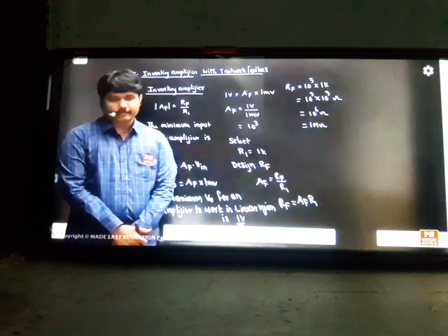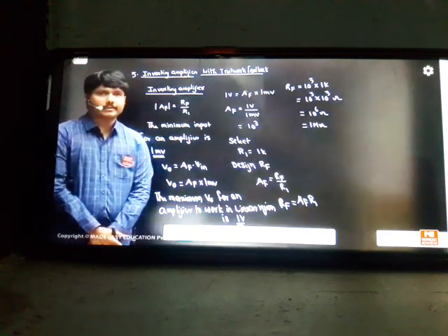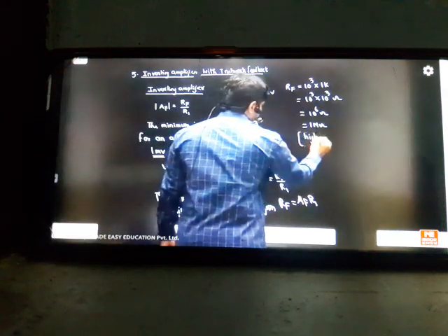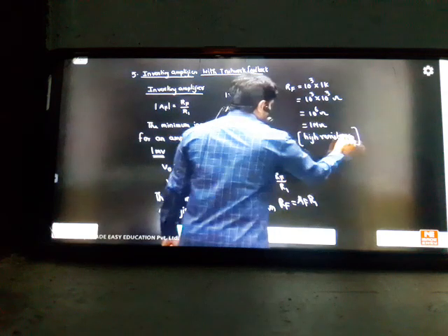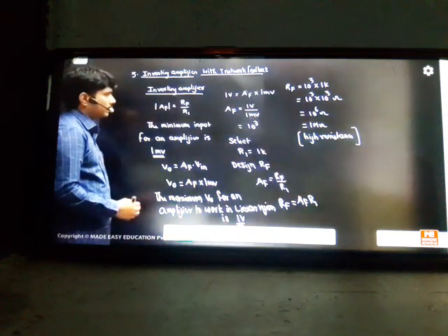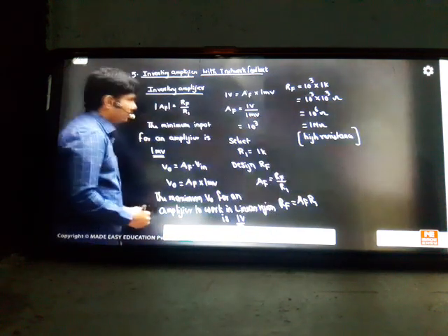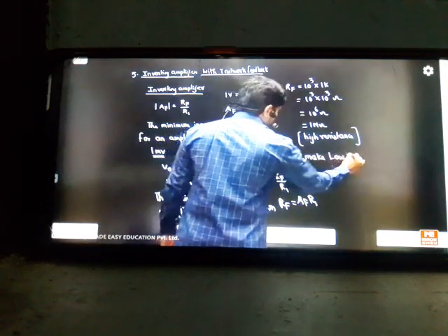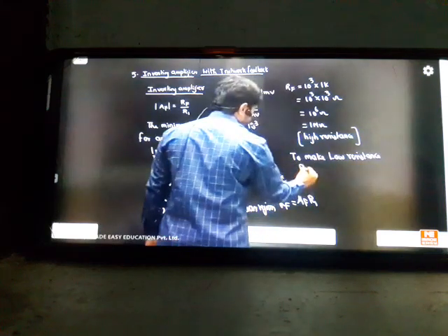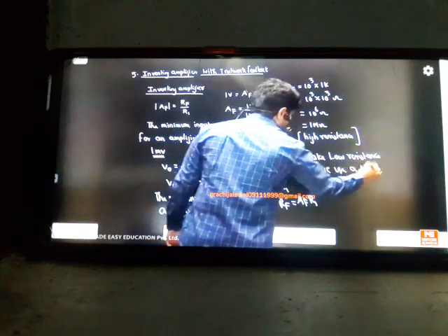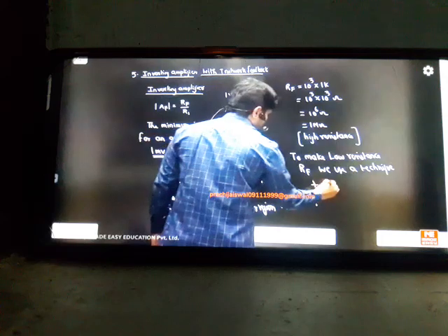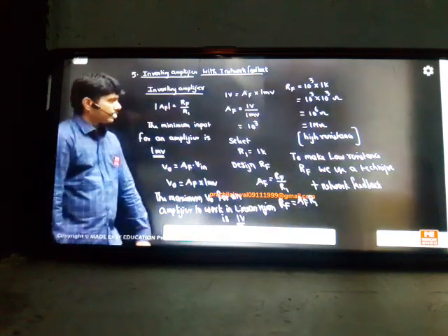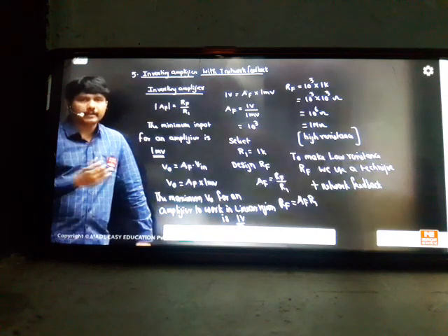That is the concept now. Let us make a high gain but with low resistances. How to design it? It becomes a high resistance for this requirement. Then without making high resistances, how to bring the gain to a high value? To make RF a low resistance, we use a technique: T network feedback. To control this very high RF resistance, I'll design a T network technique that will make the resistors very low values and still give you the high gain.